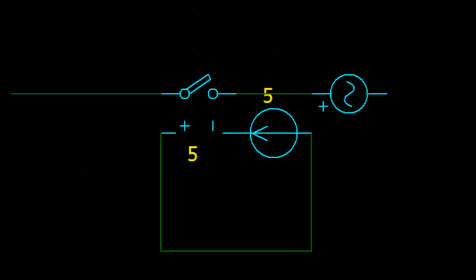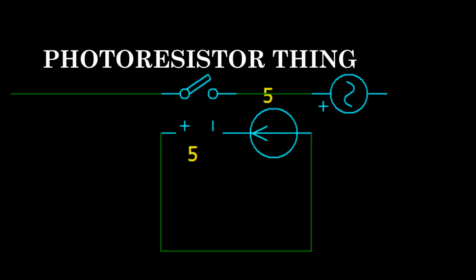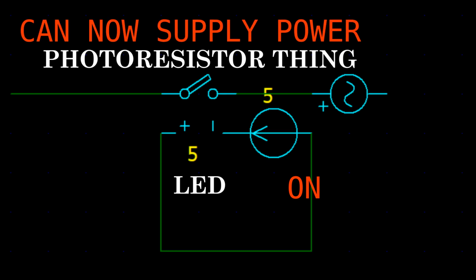To explain it better, one side of the optocoupler or photocoupler is a piece of silicon which reacts to light, and the other side is a light, like an LED. So when you power the LED, energy can go from one side of the photocoupler to the other, which allows us to basically do the same thing as a relay.